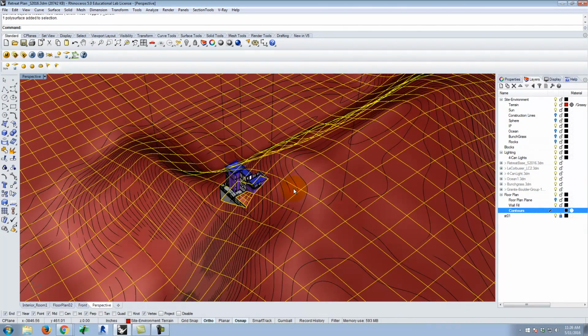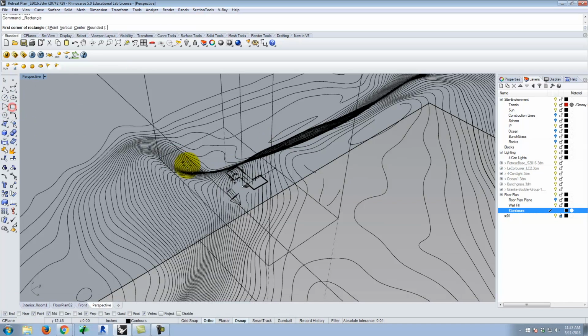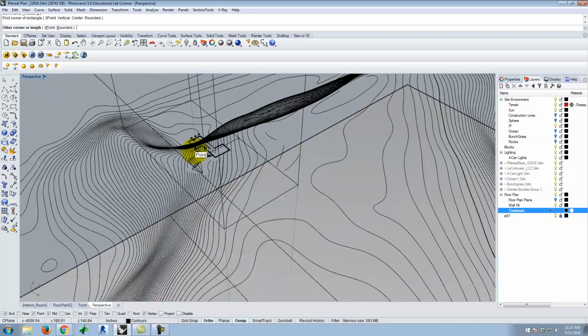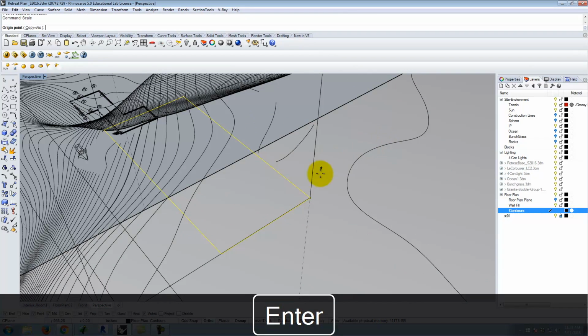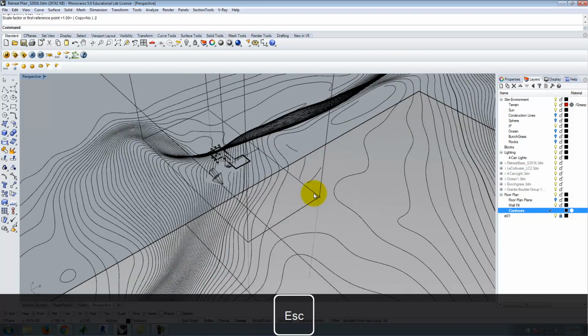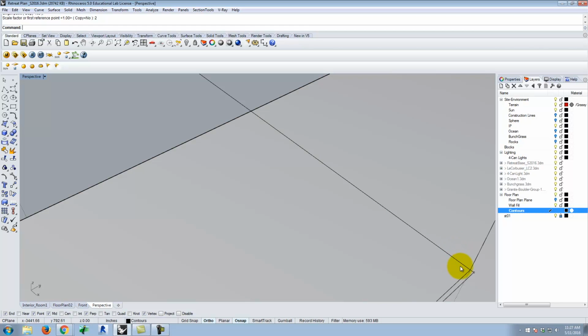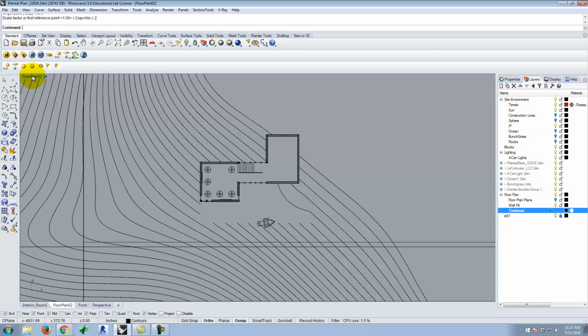And sometimes it's necessary to hide a few of the objects while we do this. So I just type hide. And now I can draw a nice little rectangle that goes from that point to that point. Then I'm going to scale from that point to, so that it fills up my whole view. It has to do with the fact that I minimized this floor plan instead of maximizing it, I believe. So we should be OK at this point.